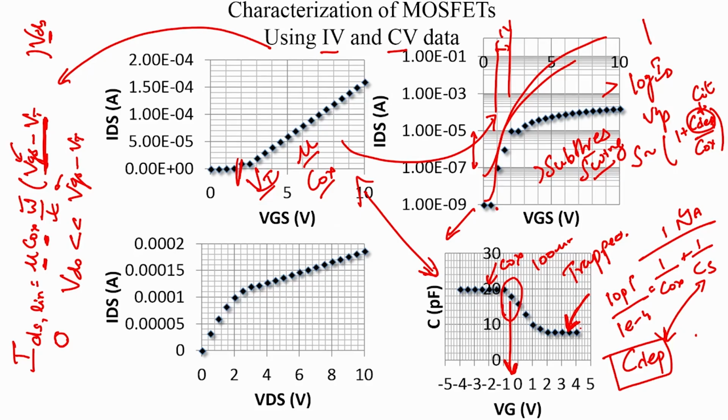You can identify the different leakage mechanisms, and we know the impact of VDS on leakage, so it becomes a very useful tool to study the mechanism of leakage. In this case, for this one characteristic it is difficult to identify the mechanism, but we can say that the leakage current is 1 nanoamp. That is the leakage current through the MOSFET. This is when the MOSFET is supposed to be off and yet it is having a current that is not 0, and that leakage is 1 nanoamp.